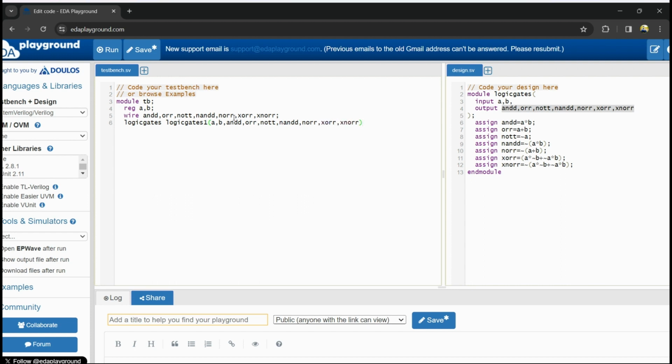These are the inputs and outputs for our logic gates, and we will start this process with the command initial begin. I will use the dumpfile command, which is used to obtain the graph file to verify the functionality of the different logic gates, and I'm saving this file with the file name file.vcd. And properly see the indentation; it is very important while writing Verilog code.